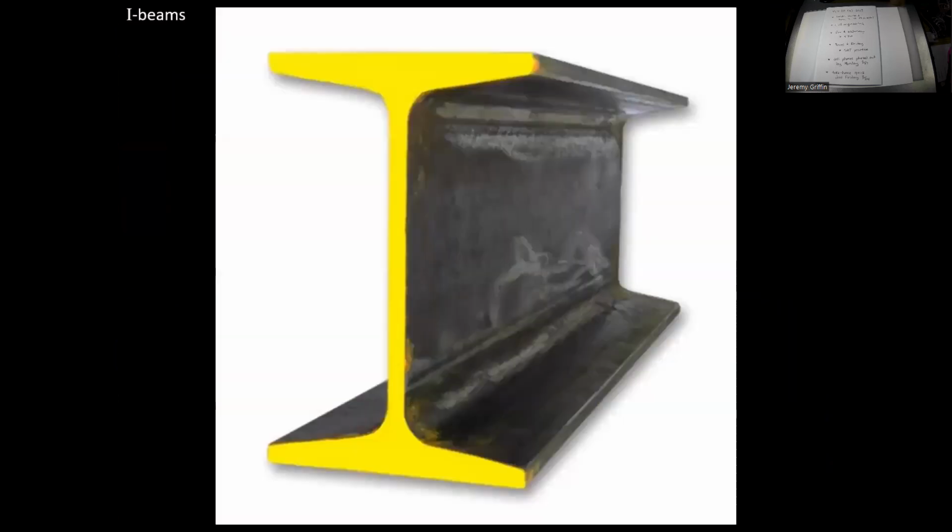Right? I-beams. So you see these used all over the place in construction. Well, what's the deal with this? So I'll give you guys a simplified example. Suppose this is on two supports, one on the left end here and one on the far right end. It's a couple supports, right? And I've got a huge weight pushing down on the top from the middle. Does this want to bend kind of like a smiley face? Want to bend, you guys think?